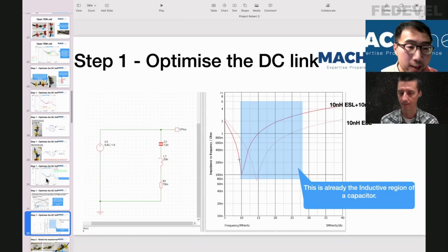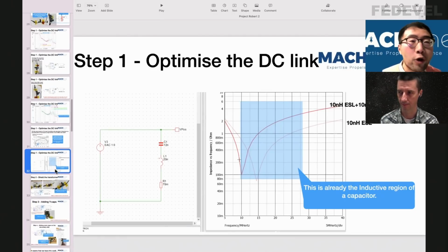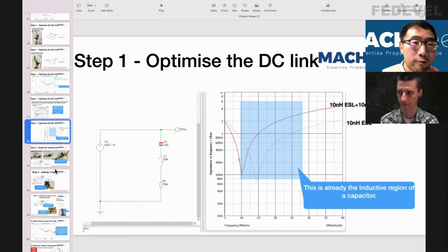So that's basically, we tried all the methods of capacitor, but because of the layout, we cannot change the layout of this small PCB, so we are limited basically. But we know that the 10 microfarad electrolytic capacitor helps. That's the first step.